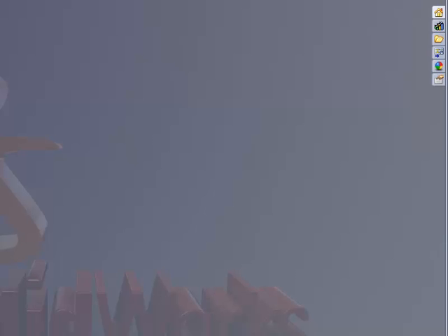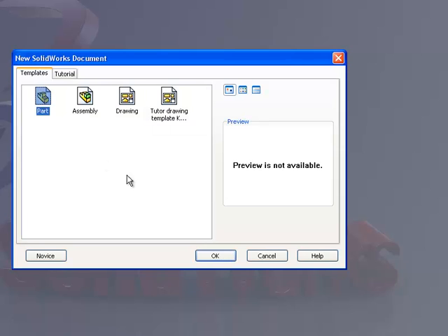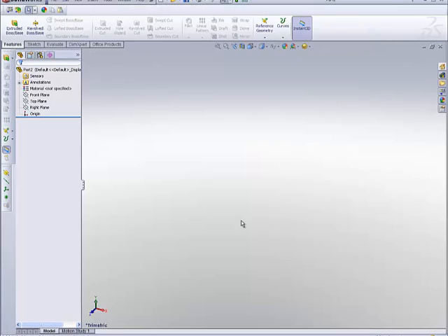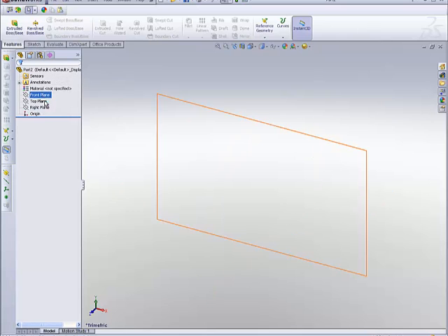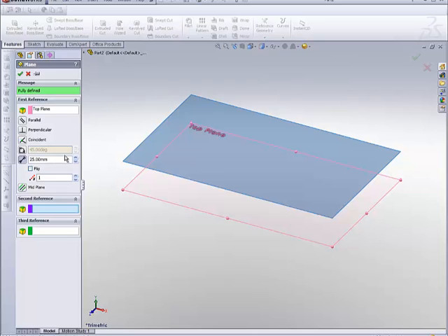Now we're going to create a funnel, and this will be created by going into New, Part, and there. So now for this, we're only going to need 2 planes, so you guys luck out. But again, click top plane, make sure it's shown, and select it, and go into here. And for this, set it to 125.